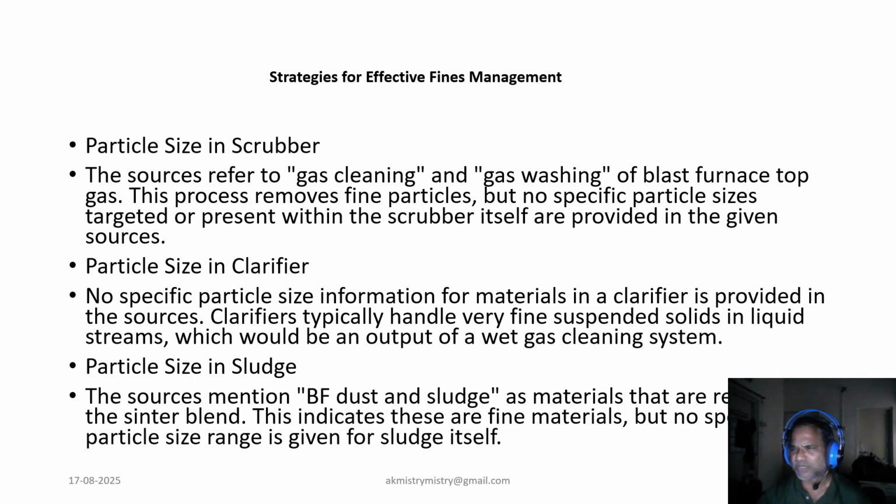The target for fines after screening in the stockhouse should be less than 3%, that is, below 5 mm. Careful bin management in the stockhouse can also prevent fines generation by filling bins gradually or operating with fewer bins to increase level more quickly. You can avoid material falling long distances and breaking down, thus reducing the generation of fines.